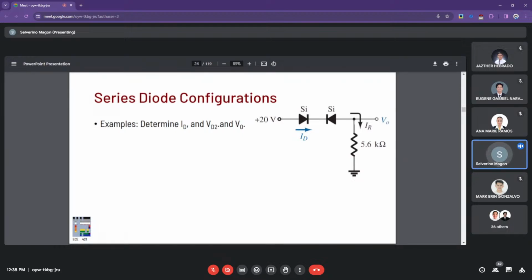So what happens there is that although this one should be forward biased and should be able to conduct, the potential cannot be reached, because the other one is deemed disconnected, since it is in a reverse bias condition and there's no voltage to exceed it to break over the breakdown region.